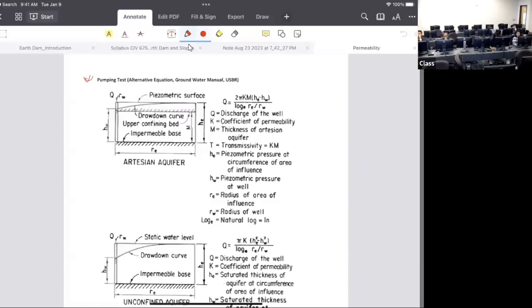Well, when you pump it, but think about it. When you do the pumping test, you don't just take the immediate results, right? You run it for some time, so when it reaches a steady condition, then you start doing it, right? Let's say at the beginning you see a very sharp drawdown curve, but later on it becomes near parallel. It will have an adjustment, a balanced condition, right? Some water will try to travel from the side and generate something.